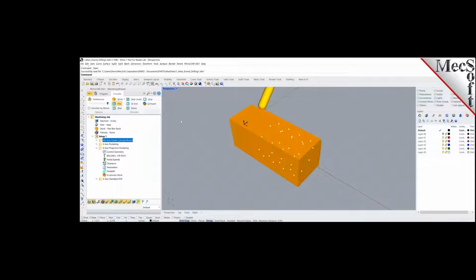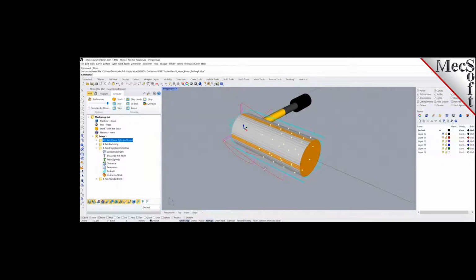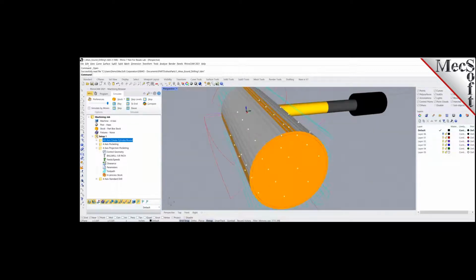So run that. It's taking that rectangular block of stock and machining a round out of it. Obviously, this comes in useful. And there's really not much interaction. It's pretty automatic. It knows where the part model is and it knows where your stock is. So it machines to the bottom and it leaves a thickness. This is the amount of thickness I specified.